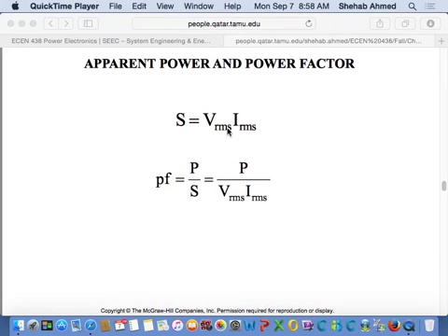Okay, so that being said, we went through the power triangle. So again, we said that the apparent power or complex power is a quantity that accounts for everything flowing in the system, and that is what you rate your equipment to. So if you open up a transformer data sheet, it will be rated to X, Y, and Z megavolt amperes or kilovolt amperes, or volt amperes. It will not be rated to so and so kilowatts. Right? Because of what we just talked about, because of the power factor. Okay, and power factor will be P over S.